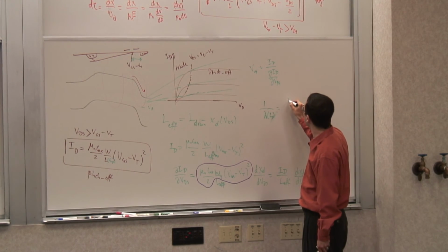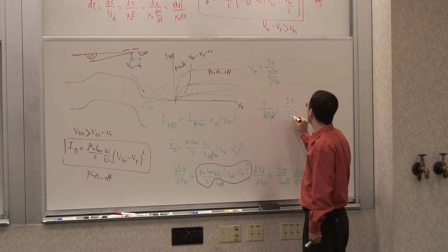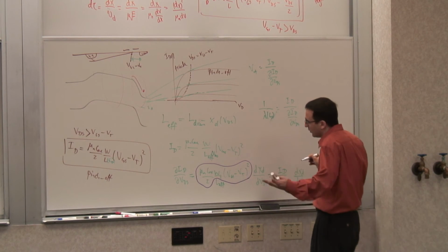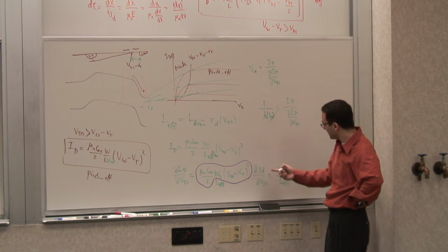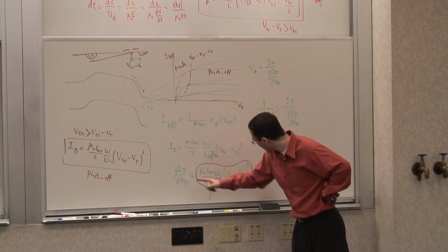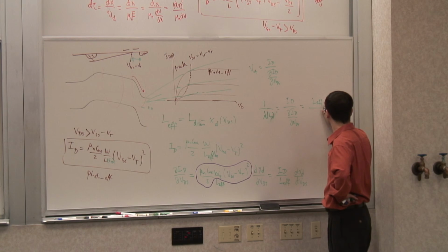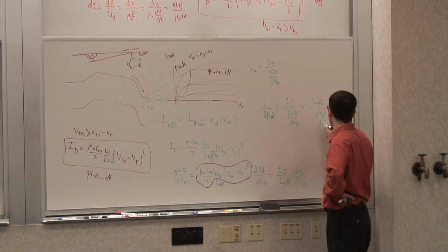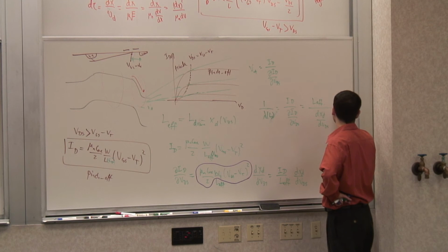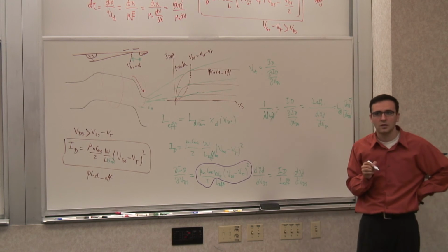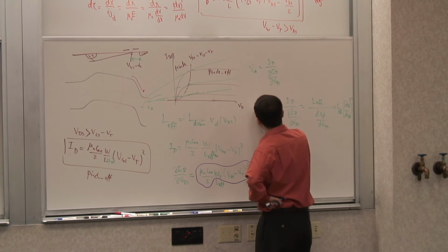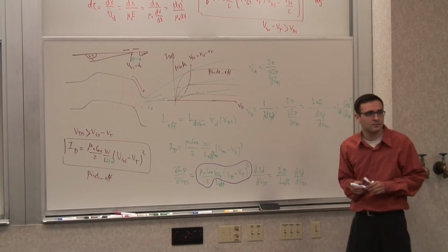And it's basically dID over dVDS, or you can even define an early voltage if you want. From this expression, it's very easy to calculate. It's basically this guy divided by that, so whatever is left will be there. So it's L effective times dx_d over dVDS, often written as L effective times dx_d/dVDS to the minus 1. So this is your so-called VA, the early voltage, if you want to define it by definition.